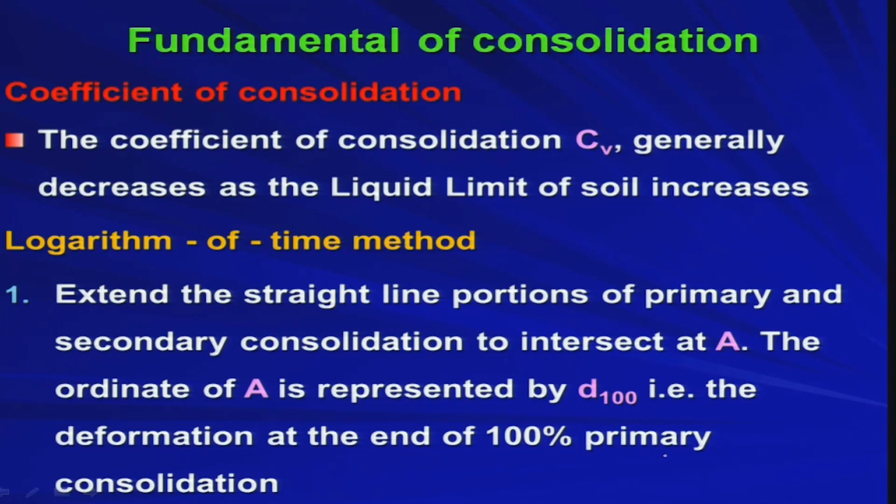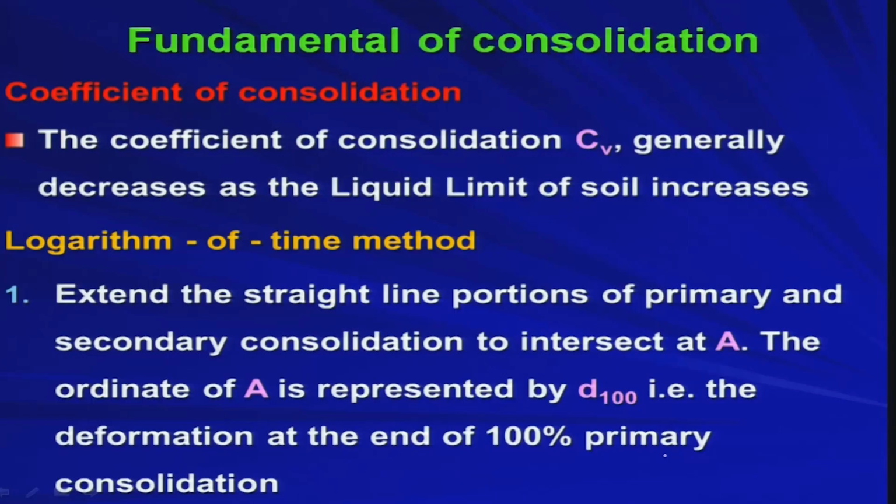Let us find out that. Before that, the coefficient of consolidation C_v generally decreases as the liquid limit of soil increases. This is true for any kind of plastic soil, that means clay type of soil.